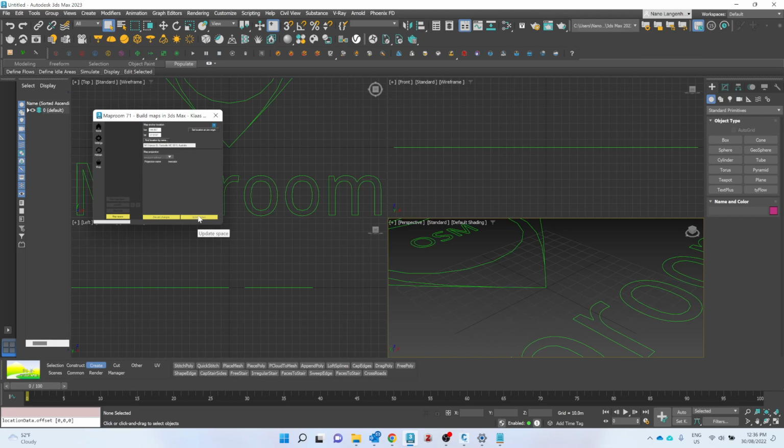So I'm going to update my space, and importantly here, the most square I can get my site is by using UTM manual, and that'll tell me that my central meridian is at 144.87 and I am in zone 55. So I'm going to update that.